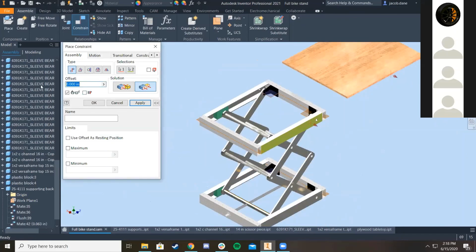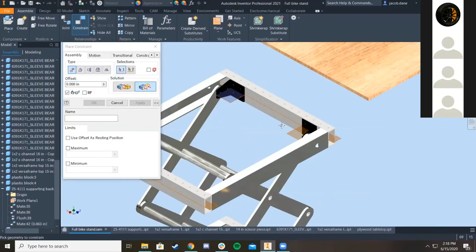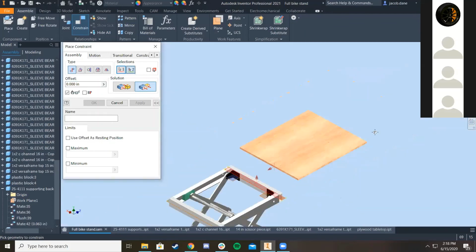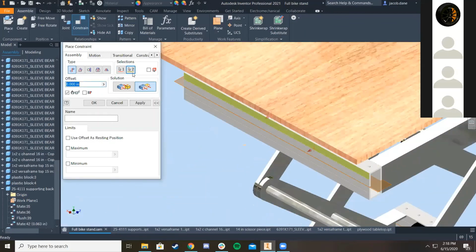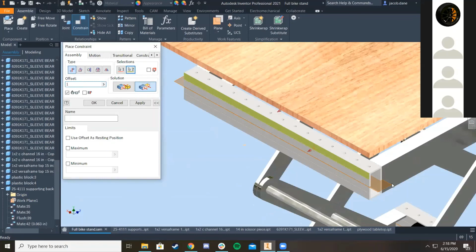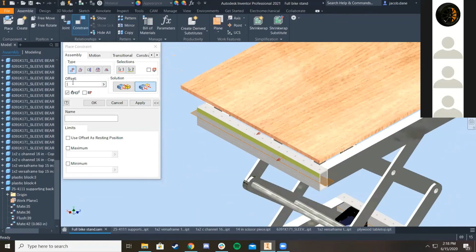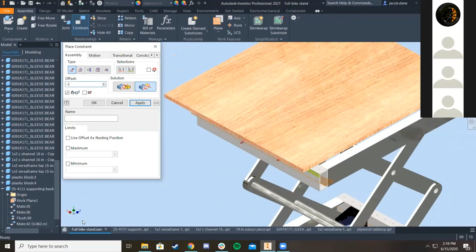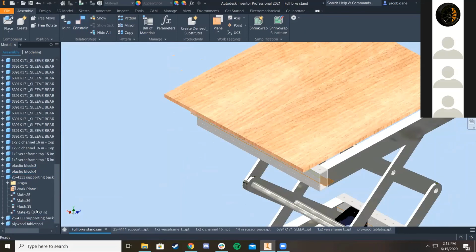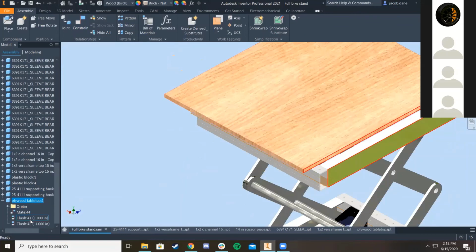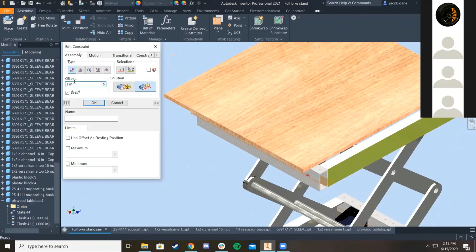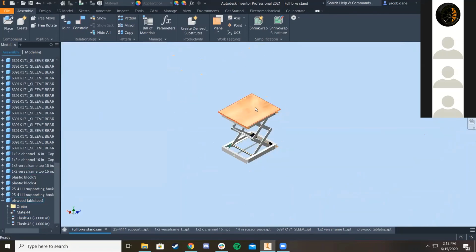And so I had a 1 inch offset, and so that's the wrong way. Actually, here, I'll leave it so you can see, because that would be hard to see in real life. So I was just clicking it, right? And I was like, oh, I know, I want a 1 inch offset. But look at that. That's offset in some dumb direction. Well, not dumb, but Autodesk is just dumb. So if I make a negative, because negative is the opposite, it'll make it very nice for you. I need to edit that. Make it negative, and there we go.